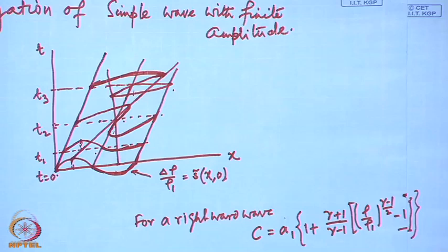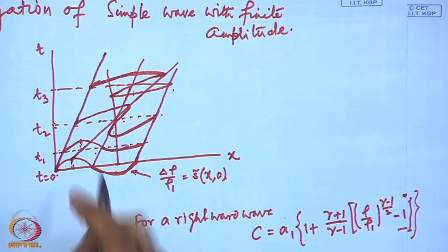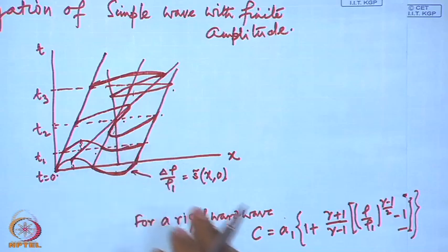and the intermediate part where the diffusive actions are considerable. However, they are not exactly in balance with the nonlinear steepening effect. The states are non-isentropic, and they can neither be considered within the isentropic relations nor with the shock relations, and the complete unsteady equations, including the viscous and heat transfer terms, are required to analyze that part. That will be somewhere between T 1 and T 2.